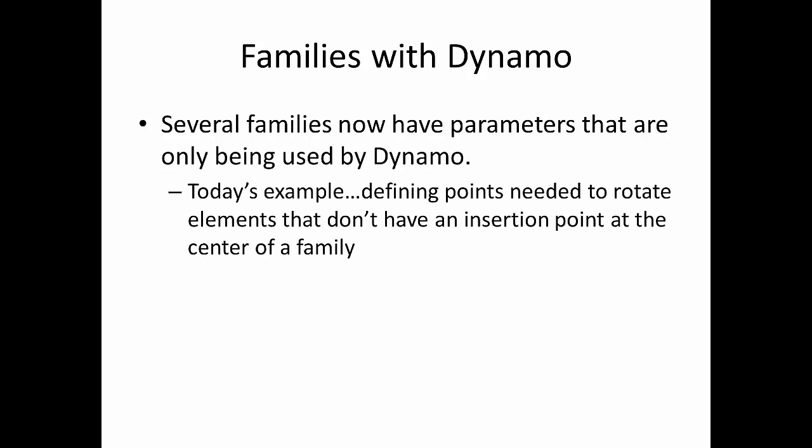I'll give you a little example. In the building we just looked at, there's probably well over 300, 400 different parts. That could be a window or a wall panel or a beam or any of the elements we mentioned before. I'm having to place these elements and rotate them, making sure they align to the outside face of sheathing so that everything's in its accurate location. So I'm rotating elements way too much, right? If you've ever dealt with placing families and rotating them in Revit, there are quite a few ways to do that inside of Dynamo. You can grab the length of the element and then find your vector point. There are just quite a few different ways to deal with it.